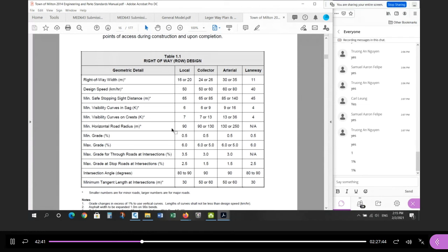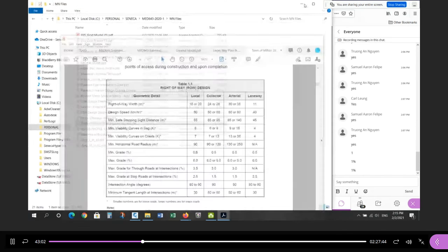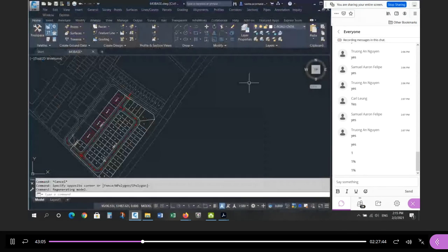Okay? When it comes to local road, most designers, not all, most designers like to avoid the vertical curves. Okay? The road is designed, the road is approved, the road is constructed. So I'm going to assume that what they did was acceptable to the municipality. I'm just going to recreate it, right? So I'm going to take the PDFs and re-engineer the Civil 3D model that represents that road. Okay, any questions about that?